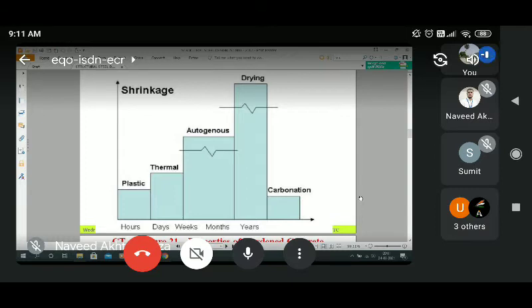First, restraint due to the aggregate, because when there is shrinkage in the paste, the aggregate restricts the shrinkage, and that leads to cracking. Then restraint due to the reinforcing bars in reinforced concrete, and restraints also in a base or a pavement for road construction, for airfields or in industrial flooring.